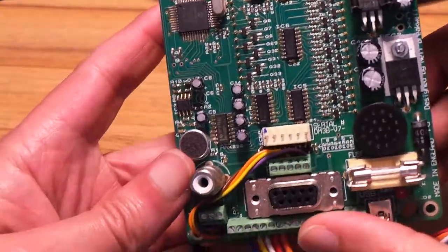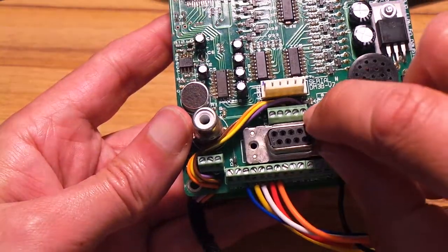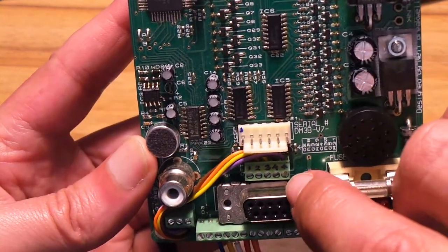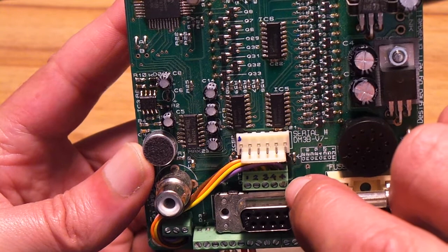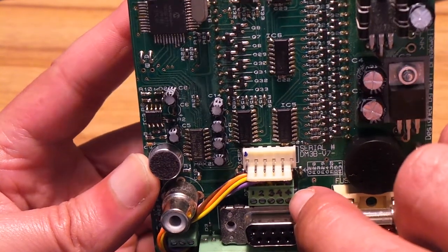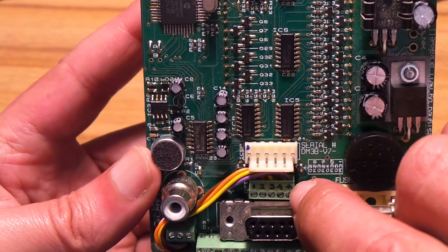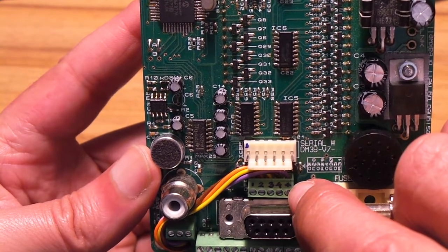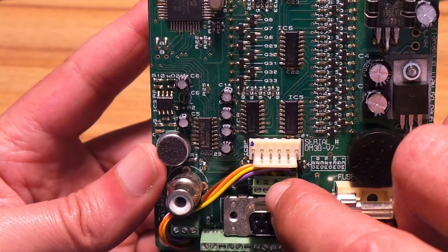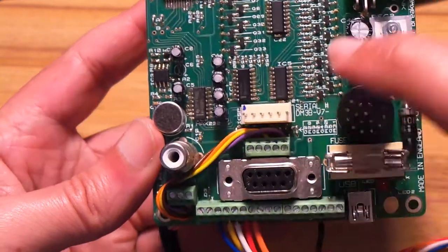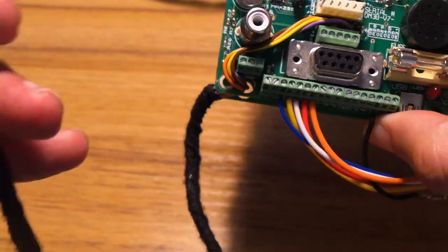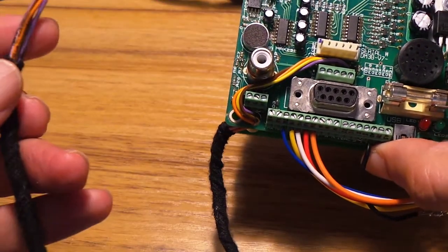We also have connections to the dash-top indicators, which go in via this 5-way connector here. We have a common power supply, a common 12 volt connection on the rightmost pin, which is labelled plus, and then we have ground switch connections to each of the individual dash-top indicators on pins 1, 2, 3 and 4, and those are just brought out on a small harness which can be connected to the dash-top indicators.